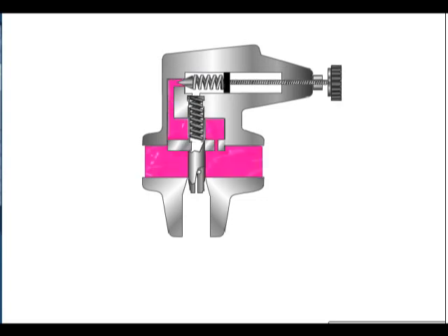Relieving action through the main spool is as follows. As long as the system pressure is less than relieving pressure set on the control knob, pressure in the main spring chamber is the same as pump line pressure because there is no flow through the control orifice, and consequently there is no pressure drop from one side of the orifice to the other. When pump line pressure rises higher than the adjustment set on the control knob, the pilot relief poppet moves off its seat. This starts oil flow from the pump line through the orifice, across the pilot relief poppet, and to the tank.